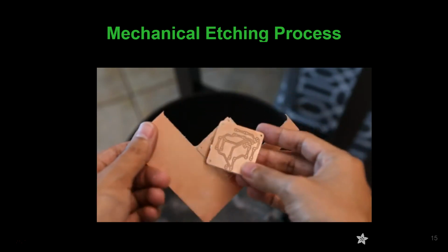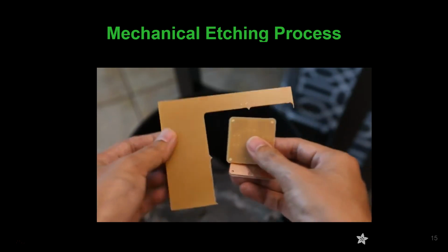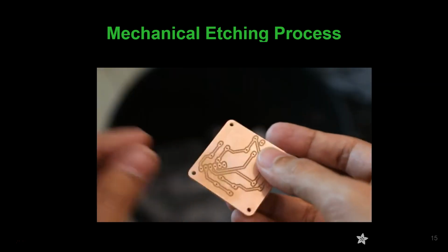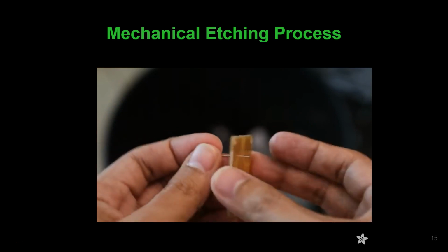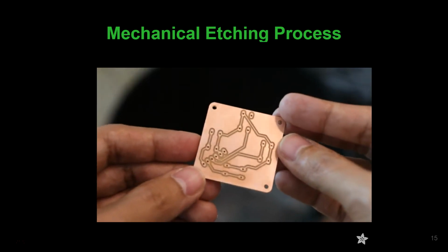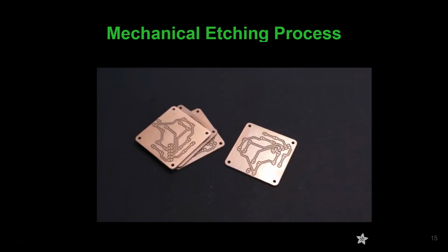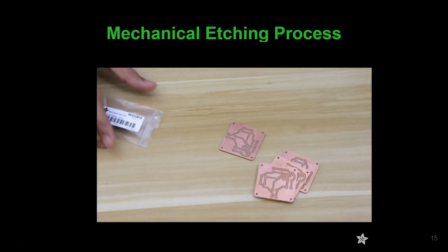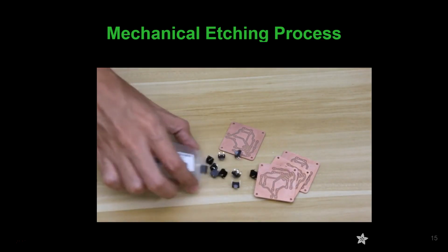I'll use this mini drill press stand along with a 0.8mm bit for the component holes and around a 1.5mm bit for the wire pads. It's important to use eye protection and a dust mask while drilling. I also keep a vacuum hose close by to remove the excess bits that tend to pile up while I'm working.